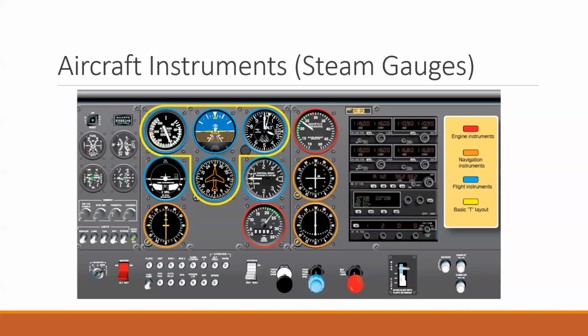You can time your descents perfectly. You can say, all right, I need to descend at 200 feet per minute over 2 miles, and I'm going a certain speed. You can time it, and you can figure out how low you're going to go given a distance or something. So you can plan your descents, and that's pretty helpful. Especially when you're starting to do IFR flights and you're doing IFR approaches, you usually pick a vertical speed to fly so that you're always going down to the correct altitude given a certain amount of time. So those are very helpful.